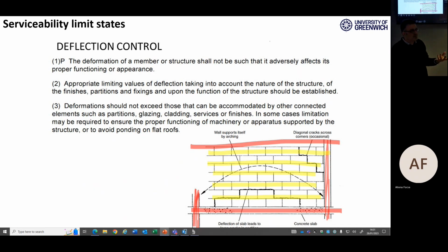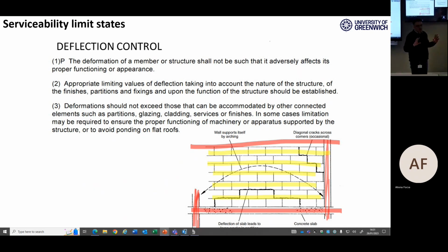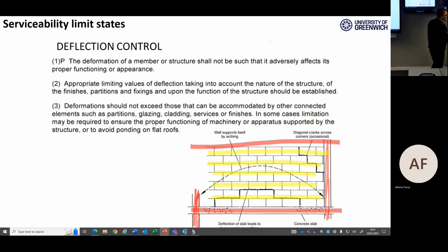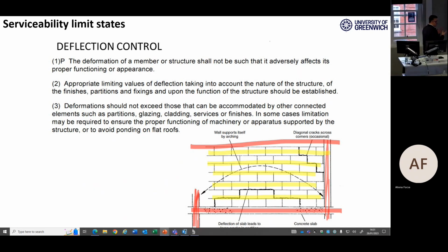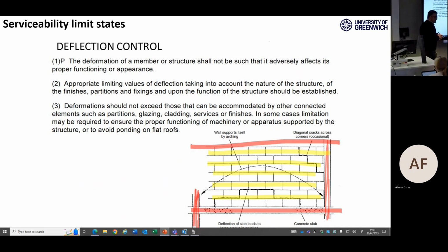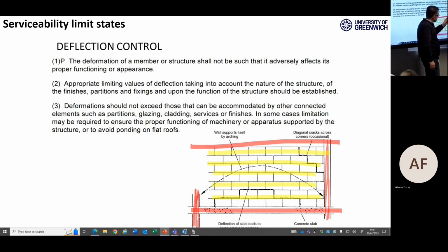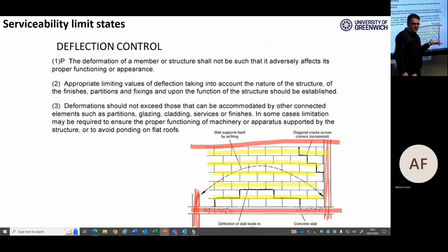Okay, there is some problem. However, there might not be any problem because the beam is carrying the load, that's fine, and that wall is not a structural wall, it's just an infill wall, or a kind of very light wall. That wall is not supposed to carry any kind of load for me. But if I see some cracks, this is scary, right?